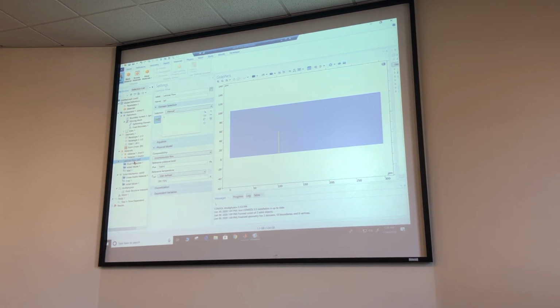And then go to materials up here, right click again, and then do another blank material for your structure. And then click on 2. Yeah, there you go. 2E5 and 0.33, and then density 7850. Yeah, and you should be all set after that.